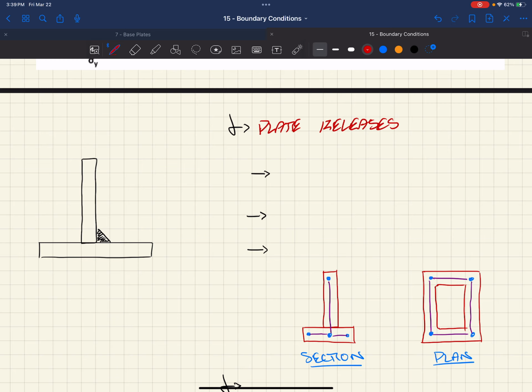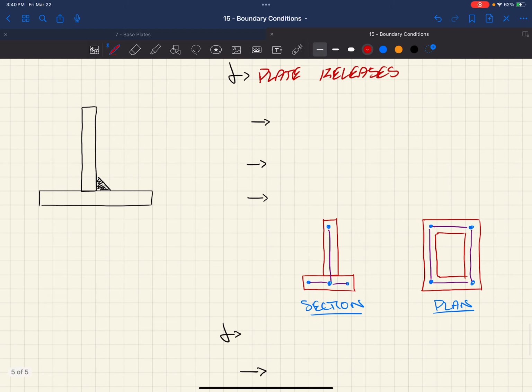Usually you use a corrugated metal deck, and you can model it as a given thickness based on stiffness, which you can establish based on engineering principles. We also use them for connections, as I mentioned. If we go to concrete, typically we use plates for wall elements or large footings, so mat slabs, slabs on grade, retaining walls, and walls for liquid or water retaining structures. Those are big for concrete.